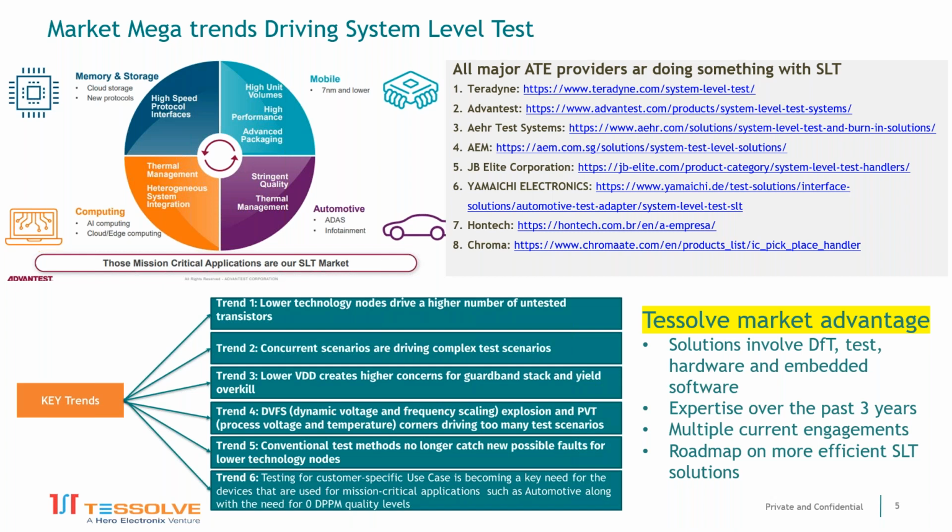You clock them and you scan out the results and you're typically looking at stuck-at faults. But they're the high volume automated test environments that Teradyne, Advantest, etc. are used to providing on the foundry floors.